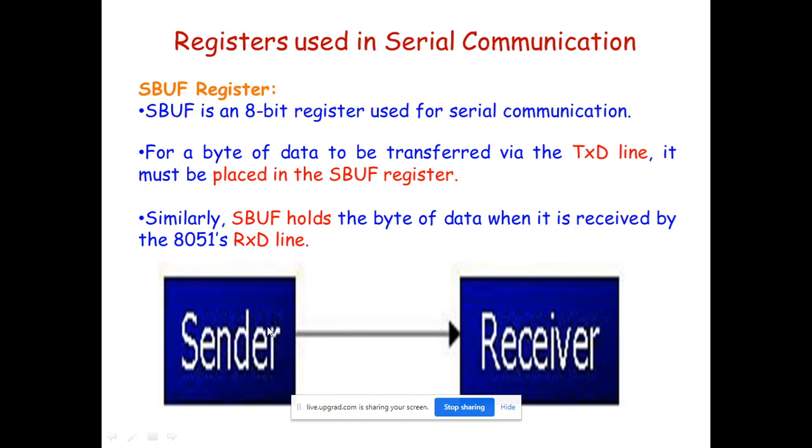When it is coming to the receiver side, one by one the data is inserted into the microcontroller and held in one of the registers. That register is called SBUF. In this fashion, one by one all 10 bits are entered, and at that time RI becomes 1. Up to that RI is 0, which indicates that reception is not completed. When RI is equal to 1, it indicates that your new data has fully arrived inside the core. In this fashion, whether data is transferred or received completely is reflected on the TI flag or RI flag.